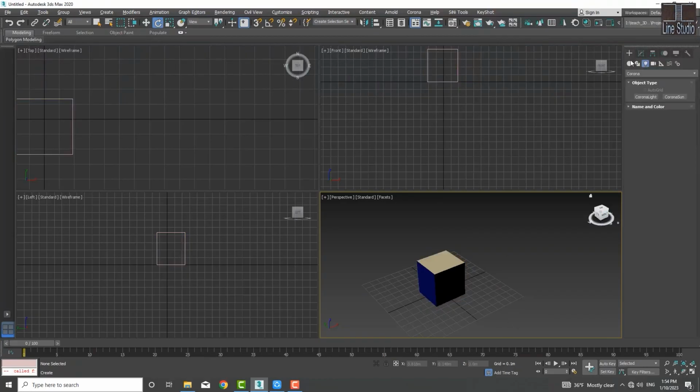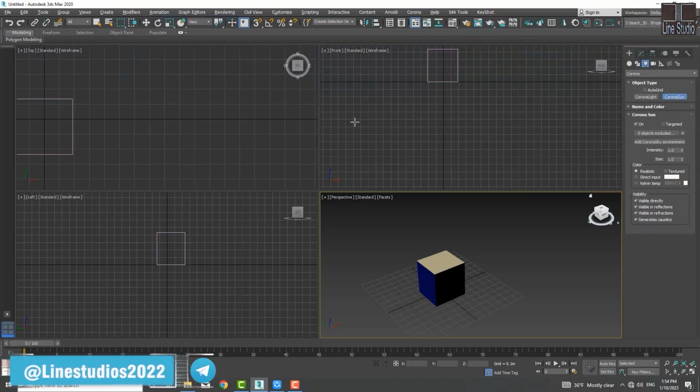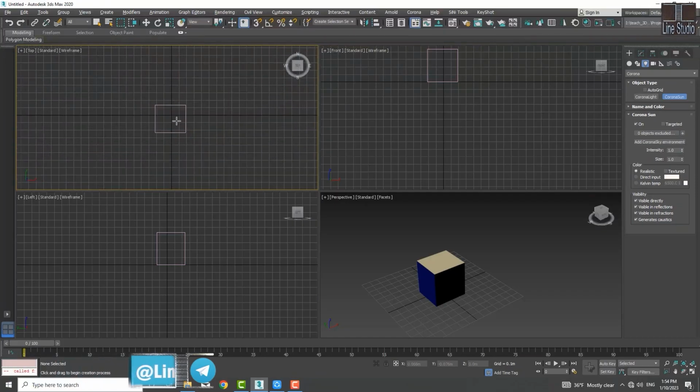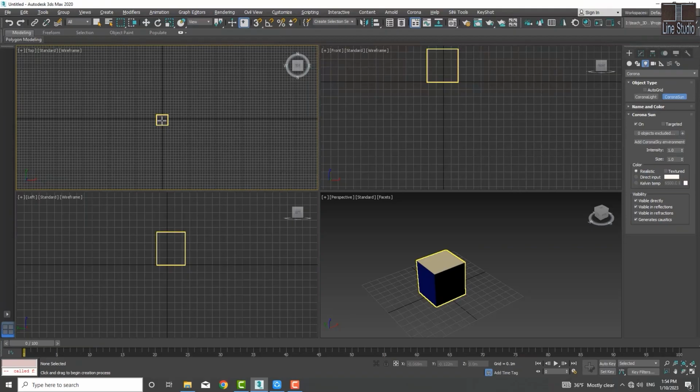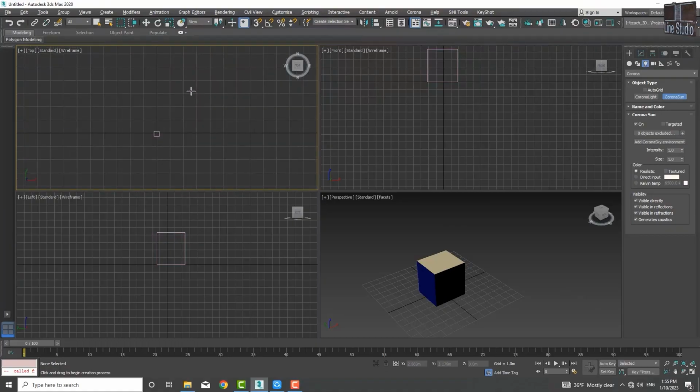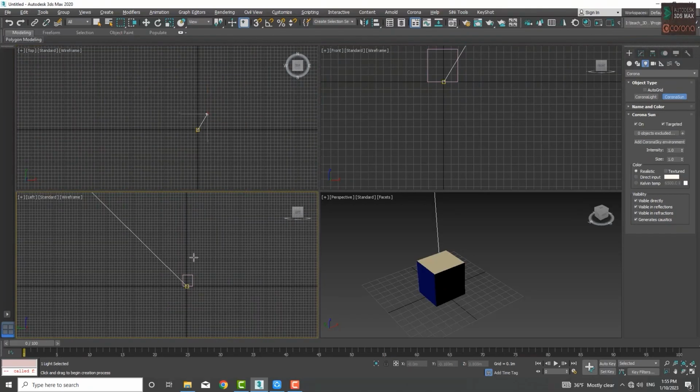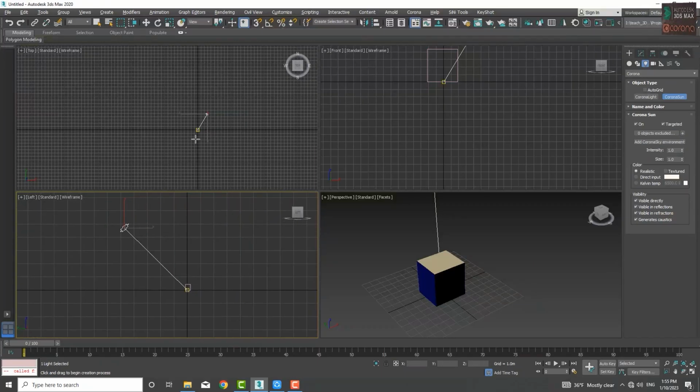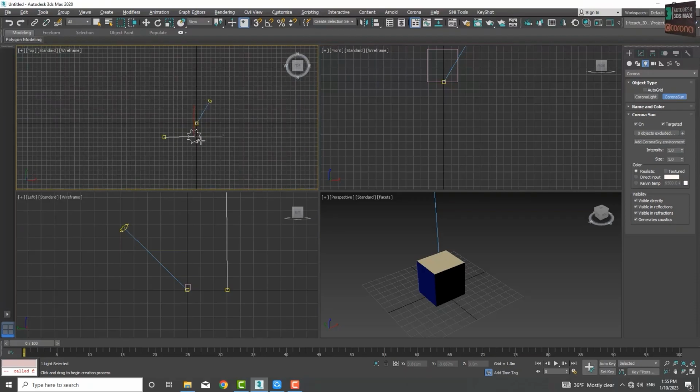Besides these, we mentioned that in the lights section, we also have Corona Sun. Corona Sun is the sun which Corona has provided for you, and you can use it in the scene. You click where your sun is placed and drag to determine the target. And then when you release the click, move the mouse to set the sun's height for you and the amount of height you want it to have. It's fine, all of these can be changed and moved.